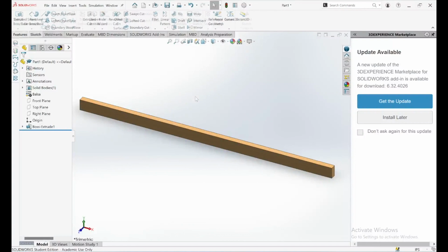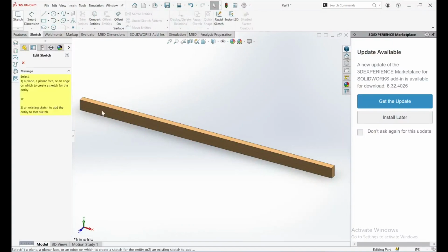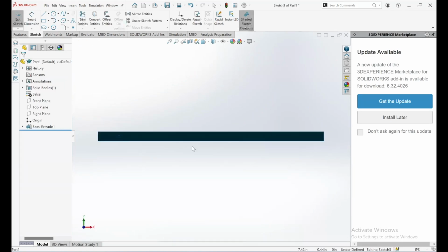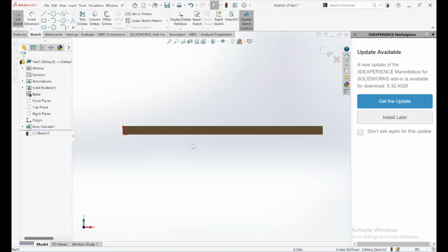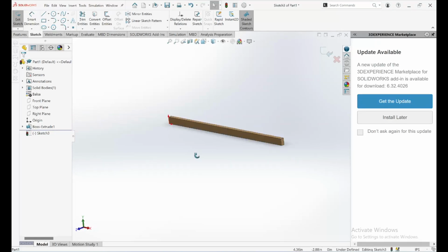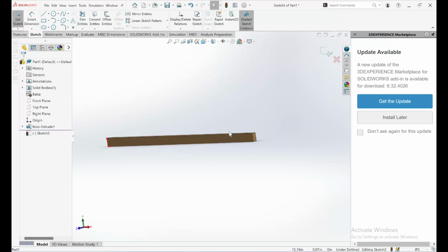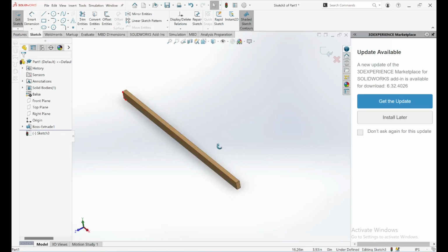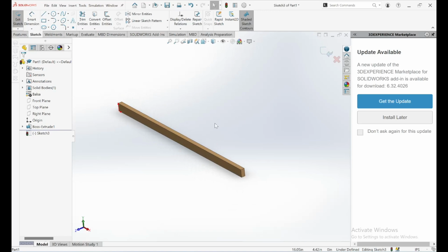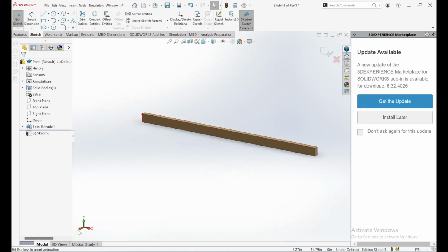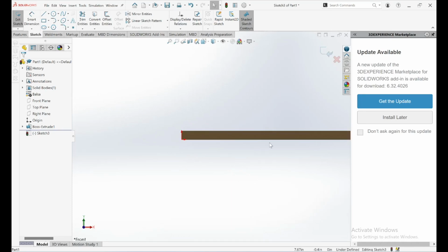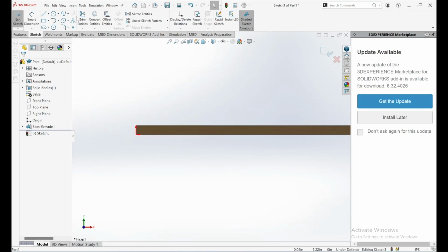Now let's add some holes. So let's go into sketch and let's sketch on this face right here. By using your scroll wheel on your mouse, you can zoom in and out. And if you click and hold your scroll mouse, you can rotate it and do a free rotation. And if you're in this view where you don't know how to get back to an on-set viewpoint of it, go down in these axes and just press the Z axis and you'll be able to get a front-on view again.